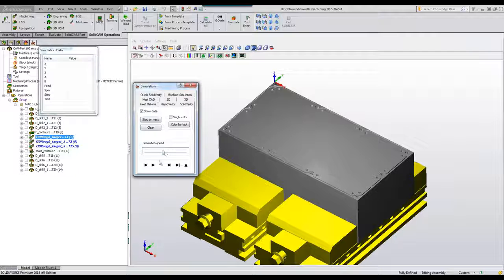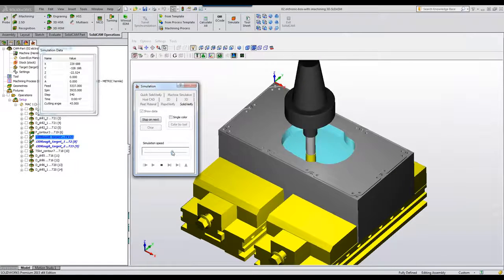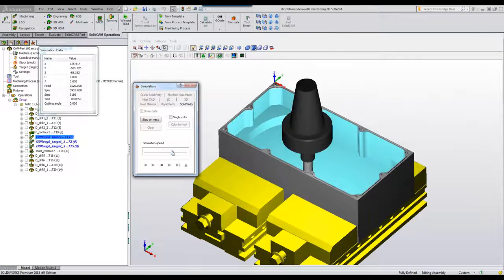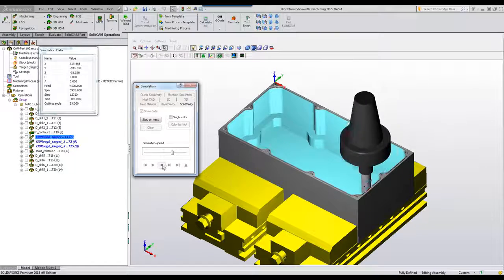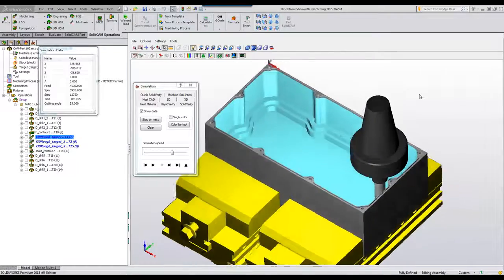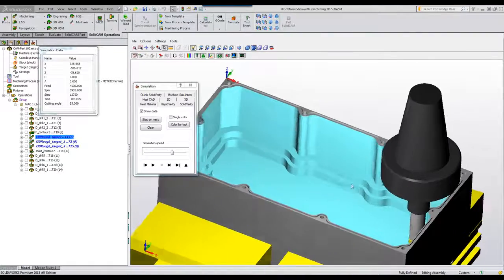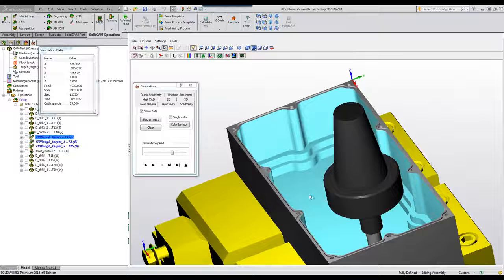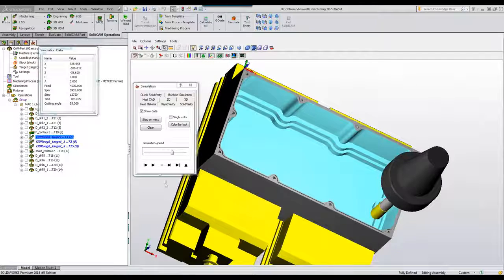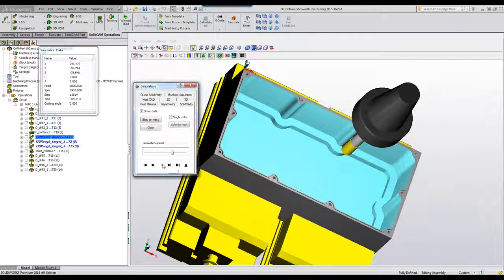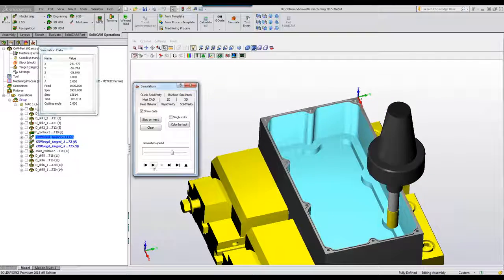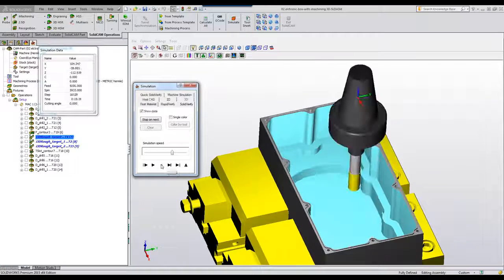It starts off very similar to the way the other one started out, doing those exact same cuts, more spiral cuts. But now look what happens when it went further down and it got too close, or it got to the area where it can't go any further in. It actually moved itself away, so this way it's clearing away all of this material with that larger end mill. Okay? Taking a look further down, you can see how it's actually machining all of those areas itself. Okay? Very bottom over there as well.